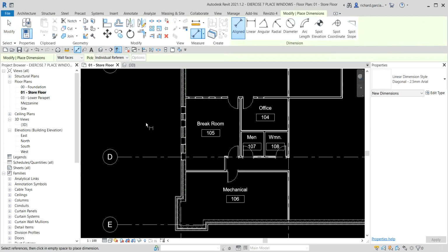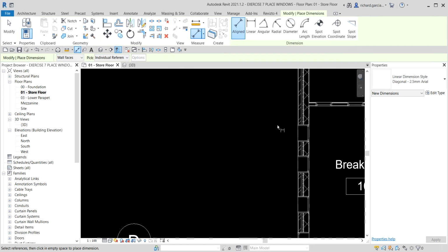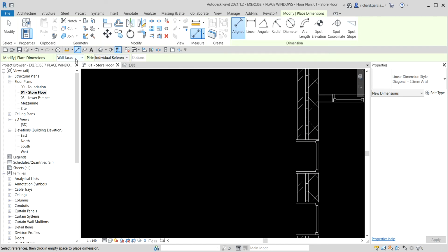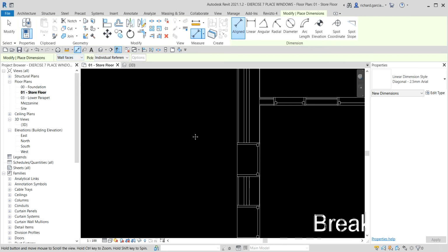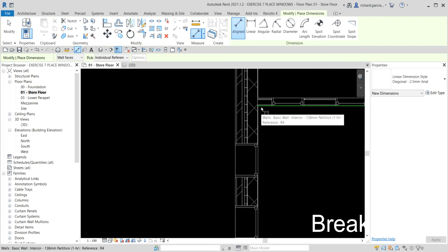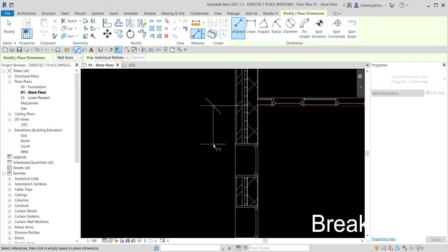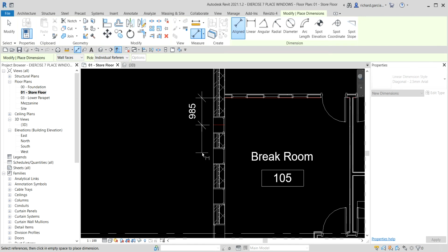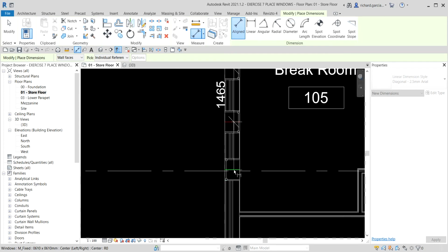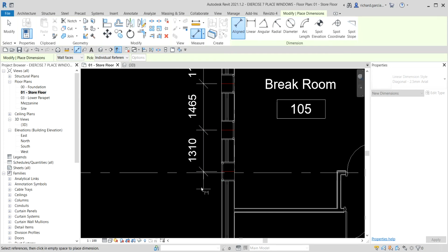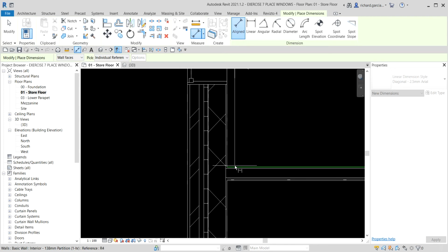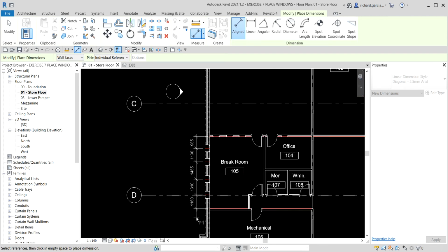And then I'm going to select the wall here. So there's a placement here as well of your wall, the justification. So you can select the wall faces so that when you move your pointer, it highlights the wall faces. So I'm going to select this, okay, like that. And then I'm going to select the midpoint or the middle of that window. Same with this. Same with this one. And same with this one here. And then I'm going to pick the inside wall like that. Okay, and then just click outside.